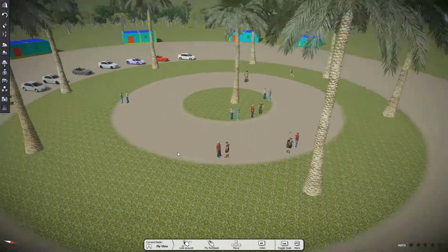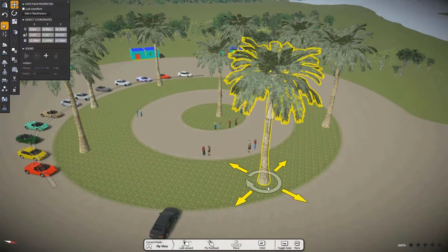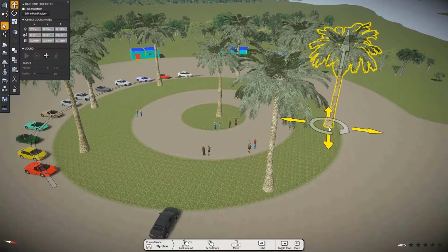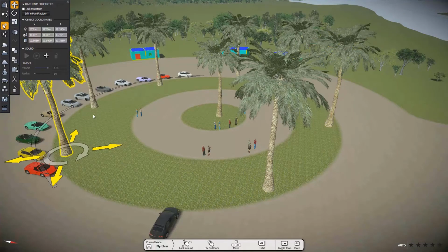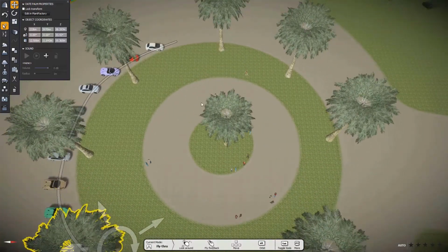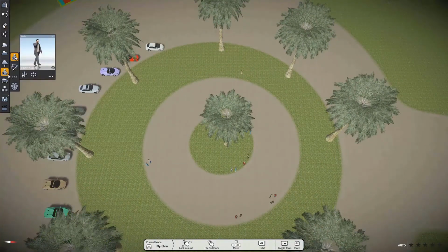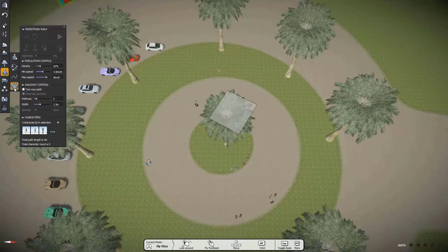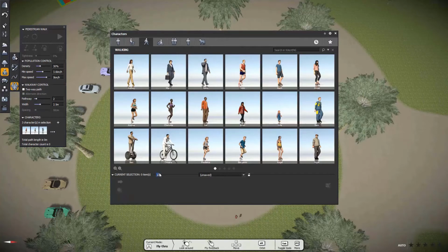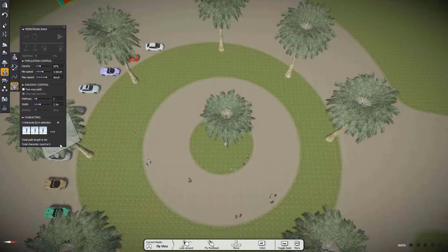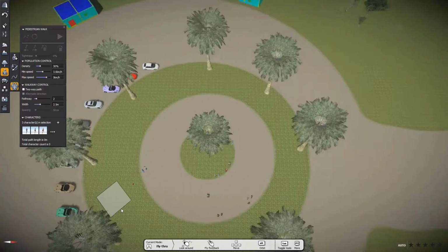Now I am showing you another great feature of LumenRT, which is to create pedestrians. So just go to the animation setting and click on the pedestrian walk. Here you can select the content. I'm just selecting the running content. Okay, now click on OK, and now you can see the pathway, whatever you want.